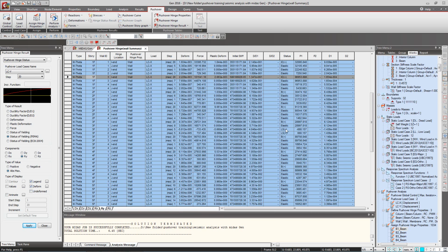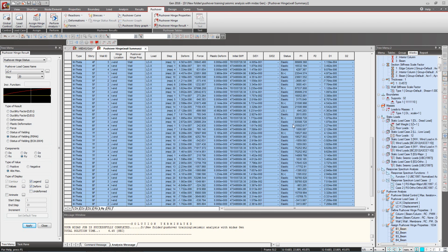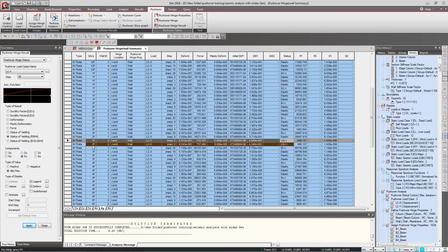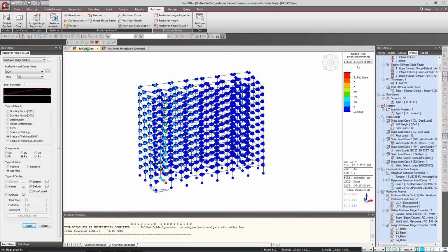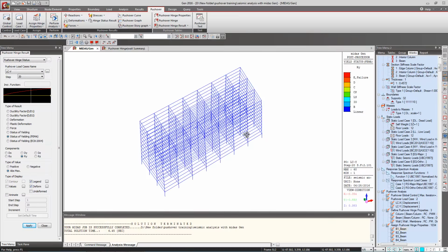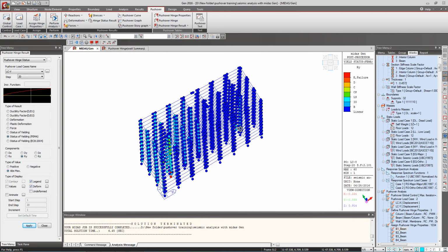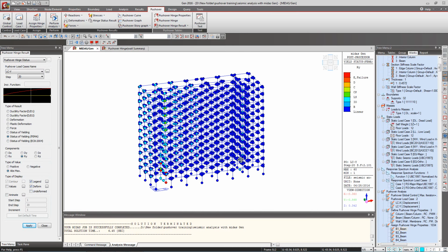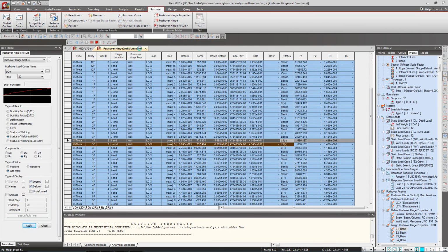And as you can see, hinges exceeding the life safety levels in here. Some are elastic, some are beyond immediate occupancy, exceeding the life safety as well. So these seriously need to be brought down. Basically these are at the 3rd floor for wall ID 2. So wall ID 2 is this particular shear wall, and at 3rd floor level, that means the failure in here. Anyways, we can check those from these tables.